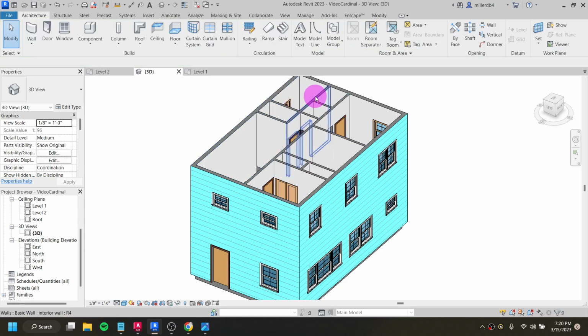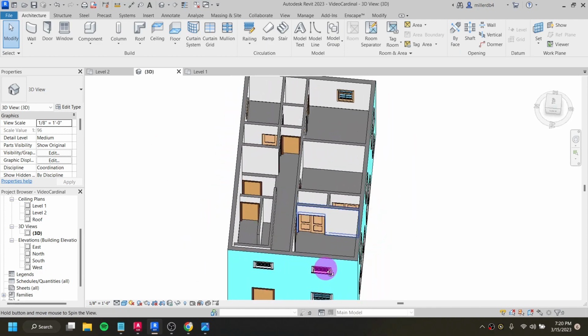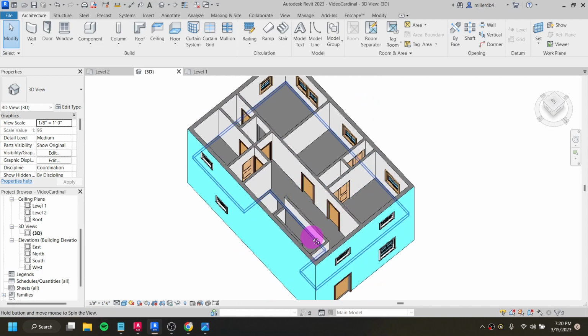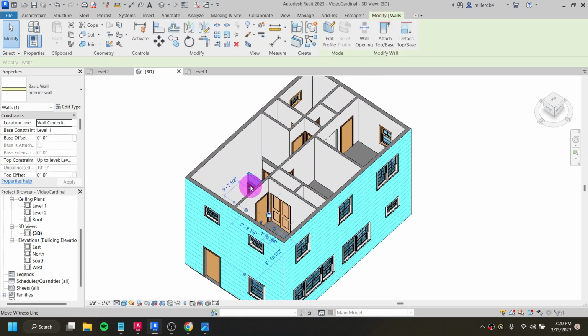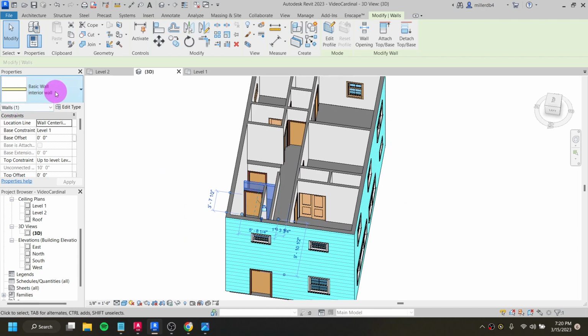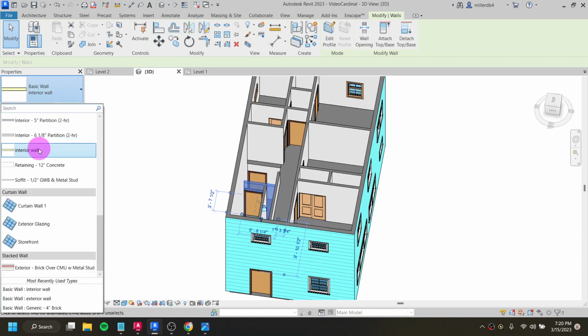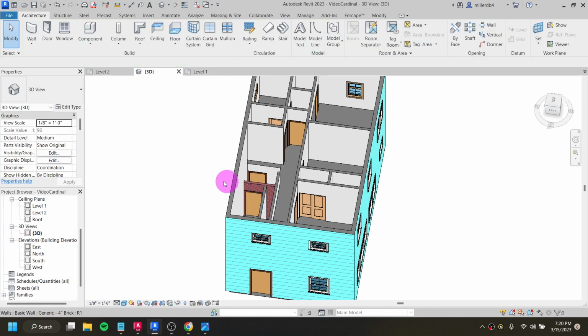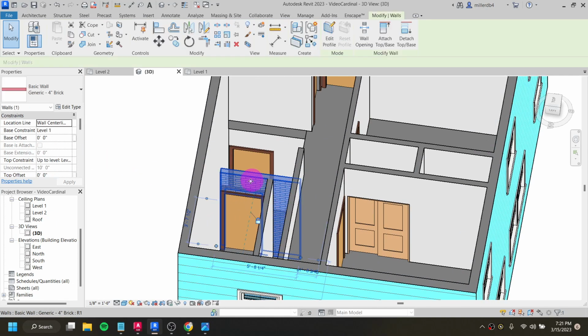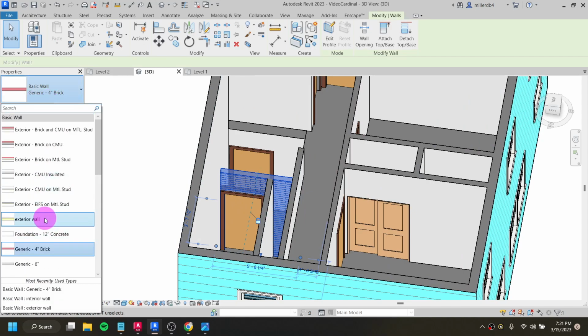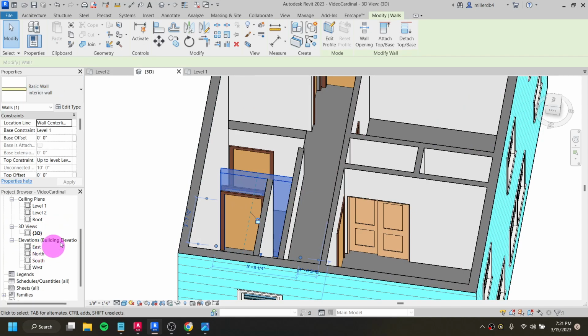Now we can see that all of my interior walls are defined. On my first floor, we can see some of the first wall in this hole here for the staircase. Because these were all originally the generic 5-inch wall, all I did was redefine its name and parameters, and it changed all of the walls associated with that family. If I decided I wanted this wall to be a little different, I can switch it to a generic brick, and now this wall is generic brick. So I can change things up as I make them. But I do want to keep it as that interior wall that I made.